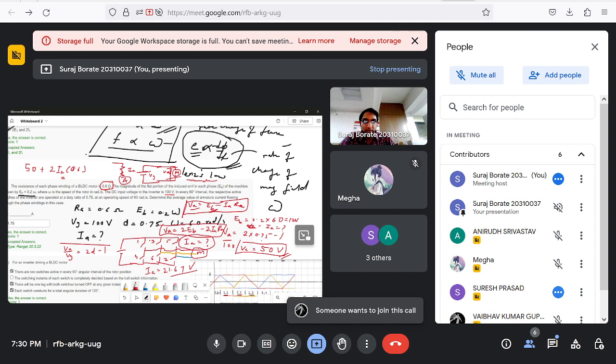But if they ask something like the magnitude of ripple torque, then that will come from delta I. Like in one of the previous sessions, we calculated the delta I. Duty ratio was given, VG divided by the duty ratio. So you have to use that formula, and then you can conclude. Got it. Thank you, sir. I've had my doubts cleared.